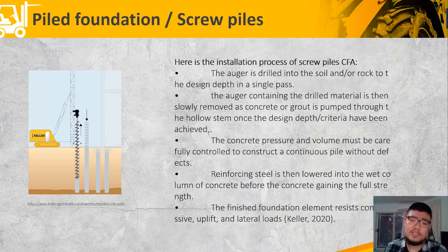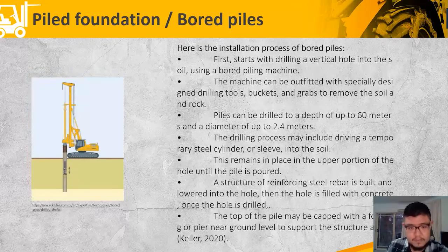So these are the different installation processes of the pile. The first one is the screw pile. As you can see in the diagram, you put the screw in first, and then you put in the concrete and then the reinforcement.